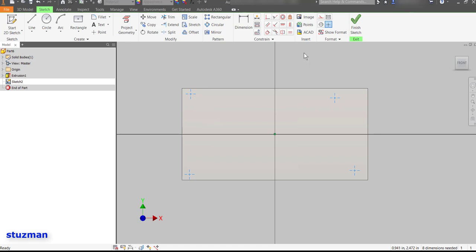Alright, so to start with, let's do it horizontal. So here's a horizontal constraint. If I click on this crosshair and I click on that, I've just told it that I want those to always be horizontal. So I'm going to do the same down here. Now just to prove that these will be horizontal, you notice that when I move one, the other one is moving because I told it to be horizontal.